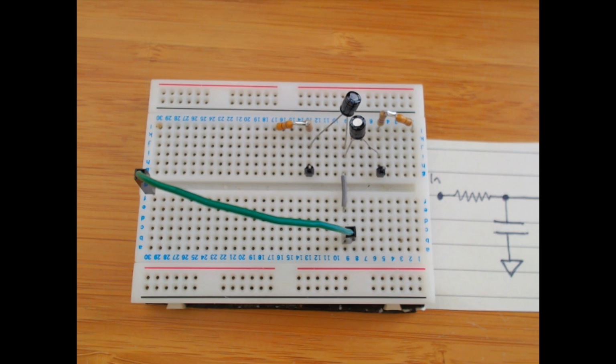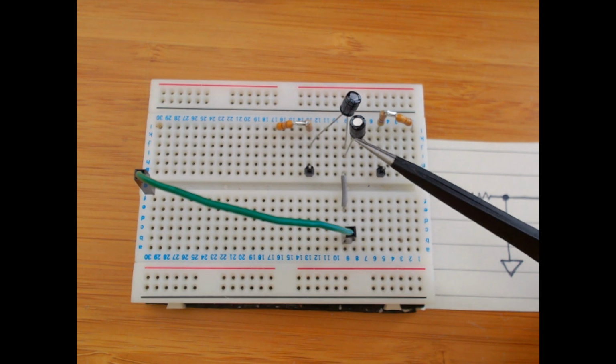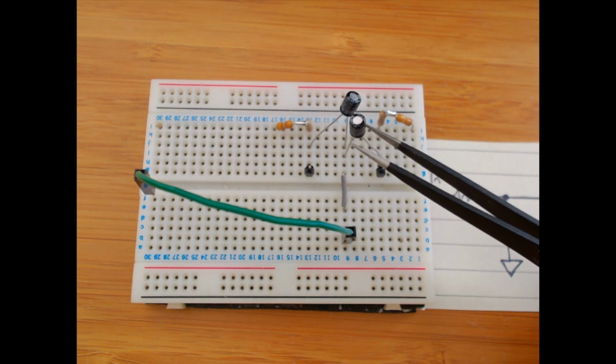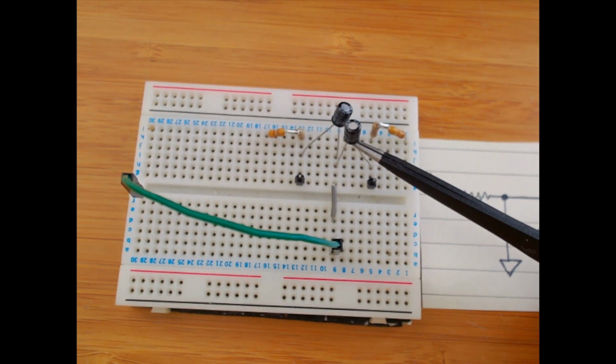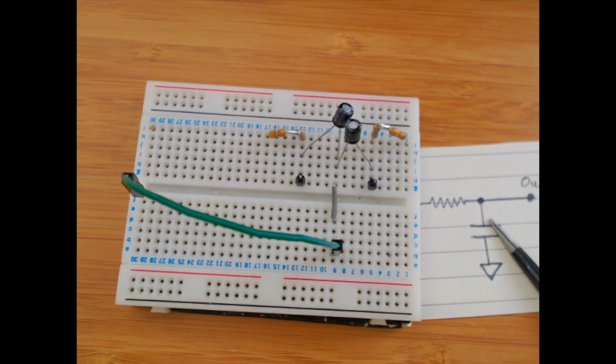Oh, and one last thing, just to emphasize how I actually got to this. I started out with a capacitor value of around 1 microfarad, right? I just figured that that's a good place to start. And then since you get to this filter through a multiplication of the resistor and the capacitor together, you can just vary the resistor until you find the right filter value.